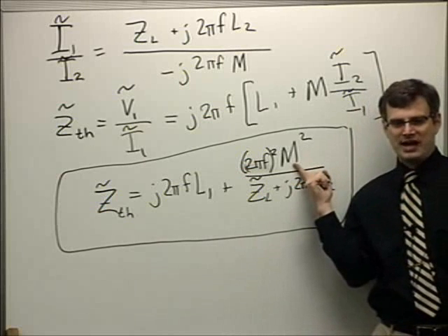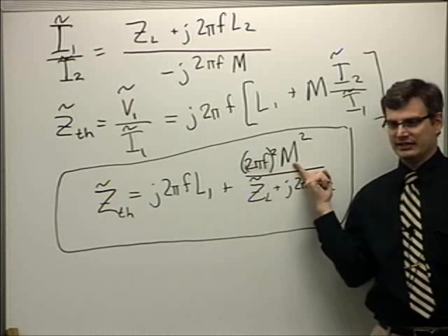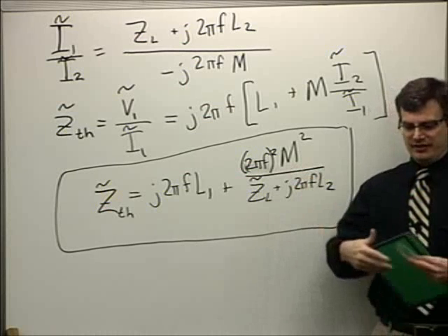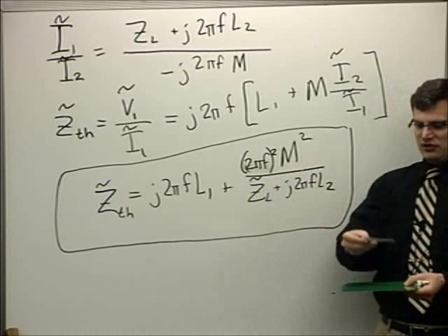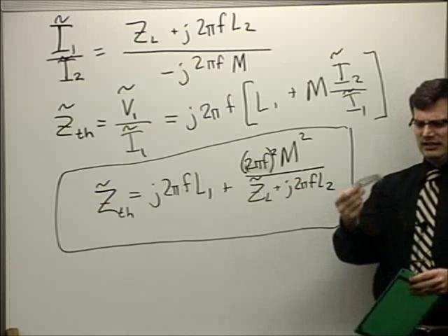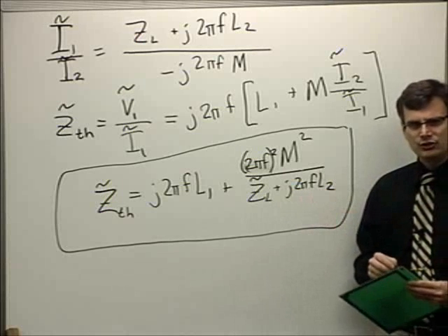The biggest M could possibly get is, M squared could possibly get is L1 times L2, right? Based on our definition. But it's probably going to be a lot smaller than that, because there's no iron core that's conducting 100% of the flux through this and this at the same time. But that's okay, because you can still do communications.